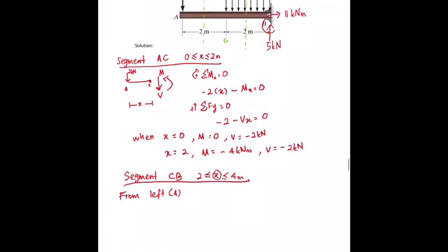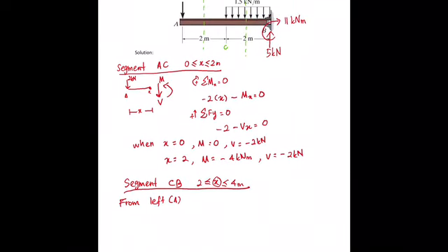This is point A. You have 2 kilonewton. And this is point C. This is half of the UDL, which is 1.5 kilonewton per meter. The distance from A to C is 2 meter. And from A to the cutting segment, the distance we name it as X. So when you cut here, then you will expose the internal forces, which are V and also a moment.